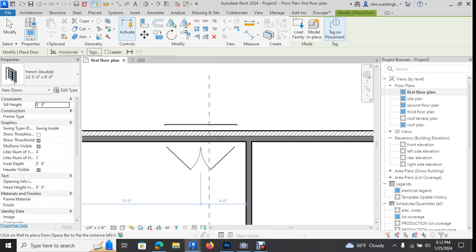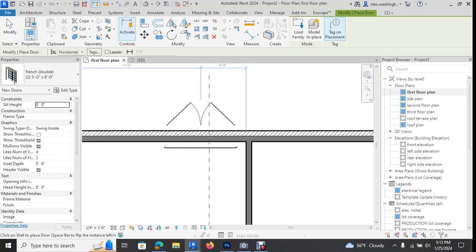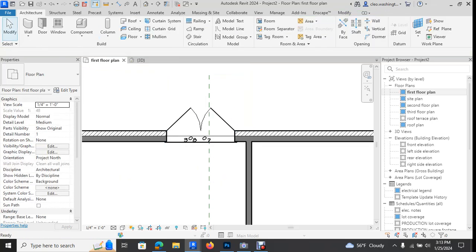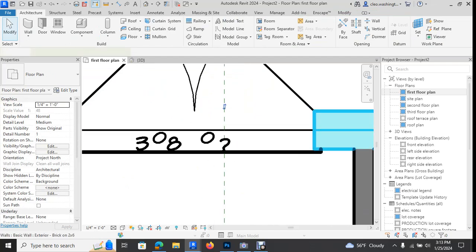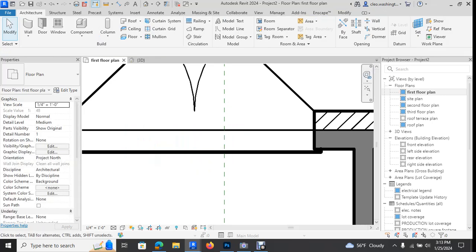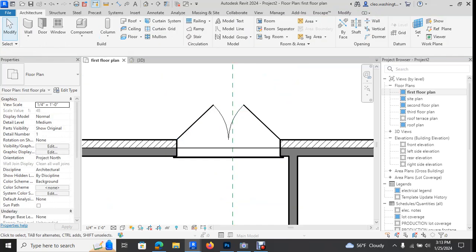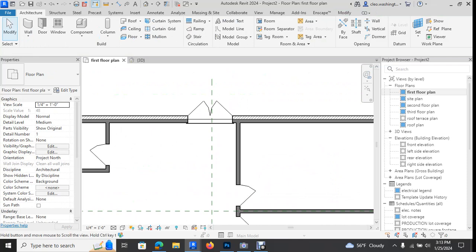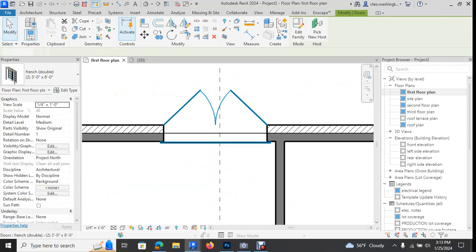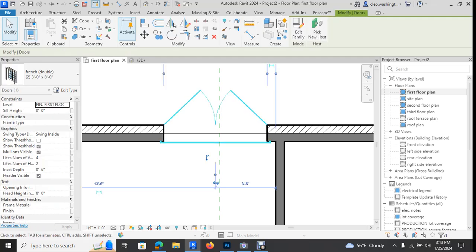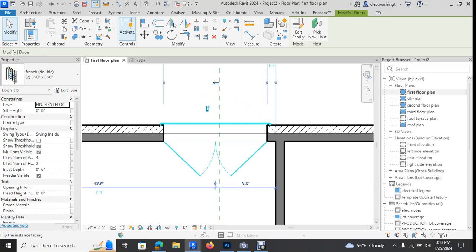So now you want to take this door and drop it in just like this, right? And you want to change the door swing, so just place it here, okay? Let me delete the tag. Now you can come here and select the door. Select this guy, 0, spacebar 6, hit enter, just to move it over, give it its proper spacing, okay? But say if you wanted this door swing to swing in, okay, when you select the door, you see these little arrows here? You can always select that arrow and it'll flip the door, okay?